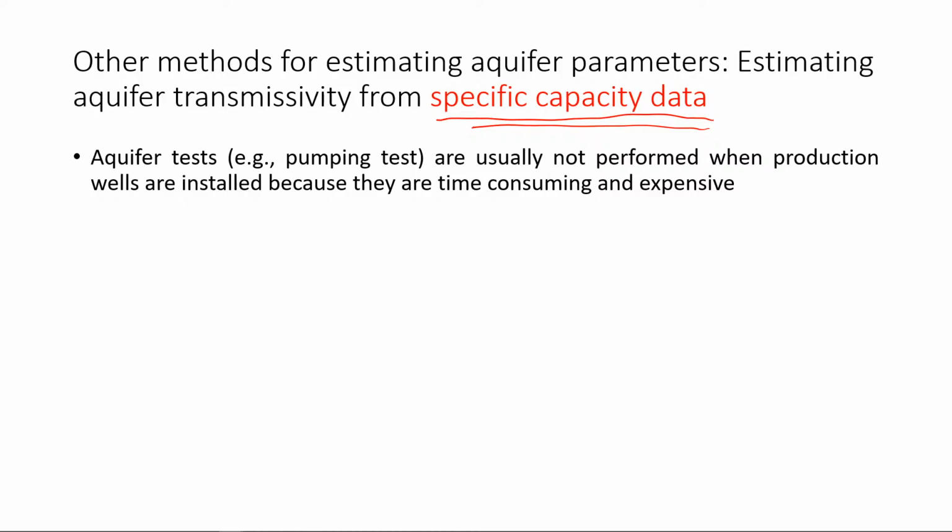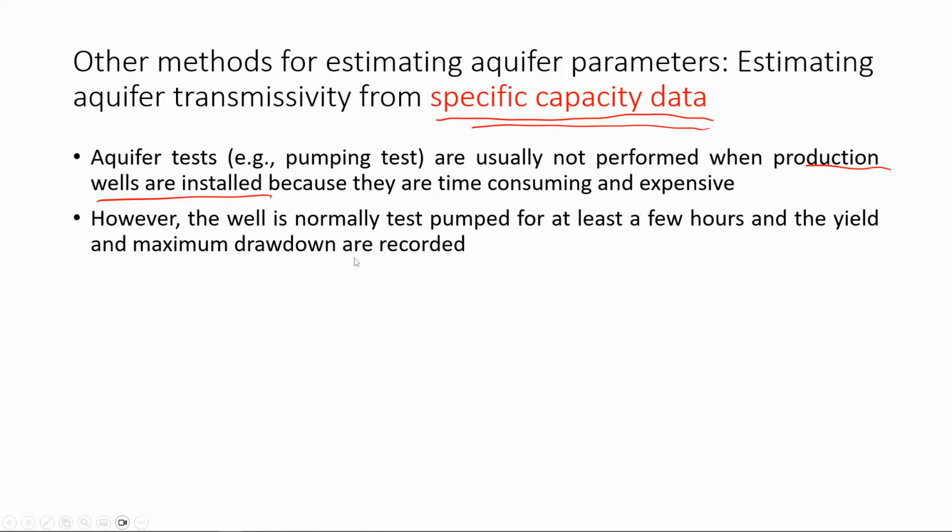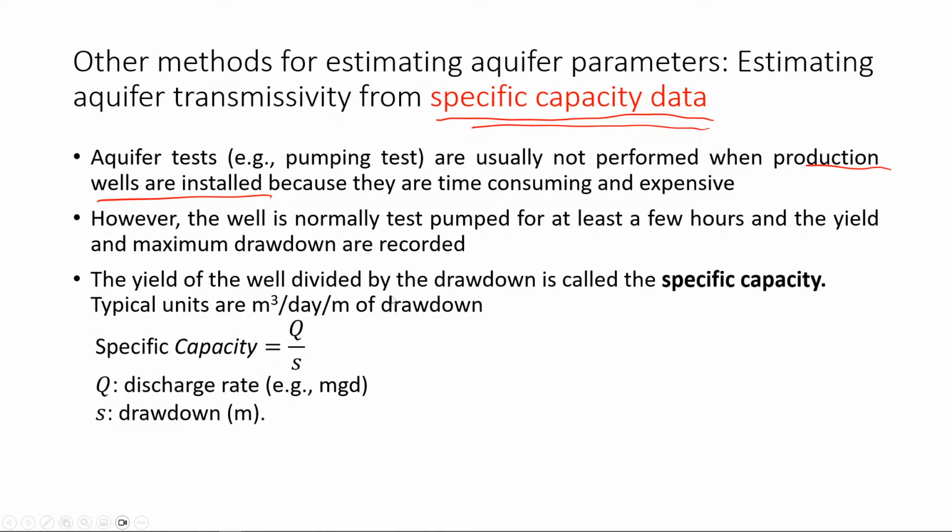Yeah, and an aquifer test like a pumping test is also very time consuming and expensive. So we conduct it before, at the planning stage, before the production well is installed. But if the production well is installed, what you can do is collect something called specific capacity data.